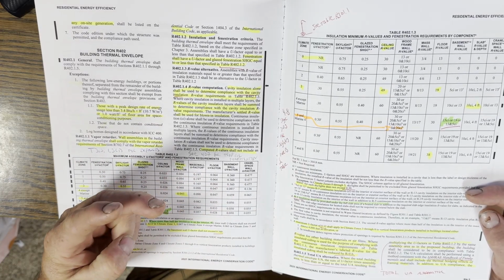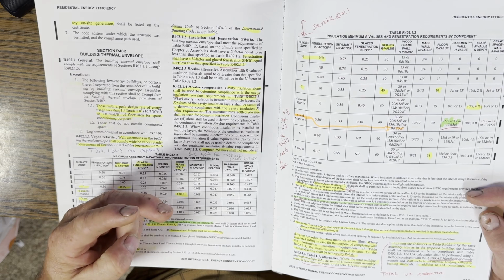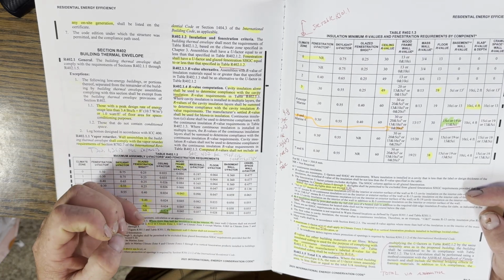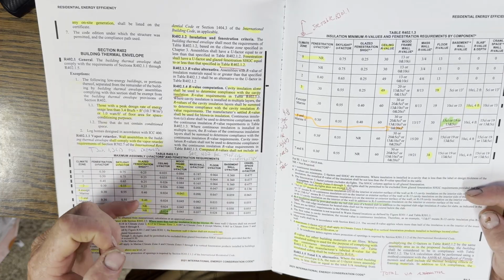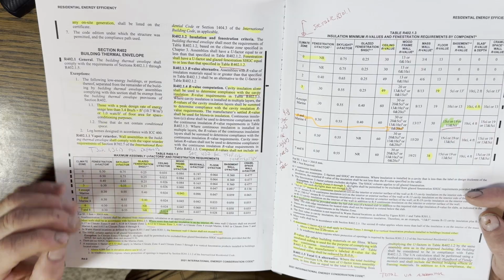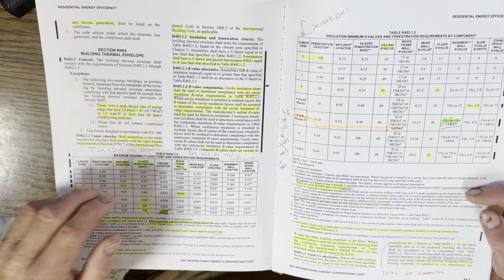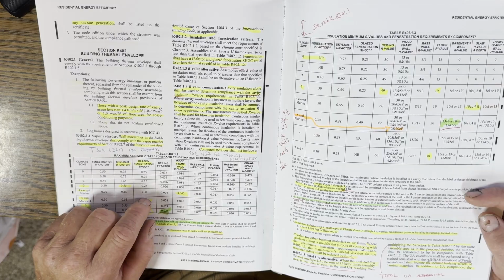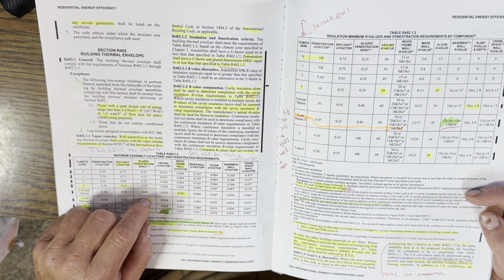Two were 6 feet by 6 feet 8 inches with a U factor of 0.54. One was a 4 by 5 with a fenestration U factor of, I think, 0.35, and the other was similarly a 4 by 5 with a U factor of 0.3 or something like that.